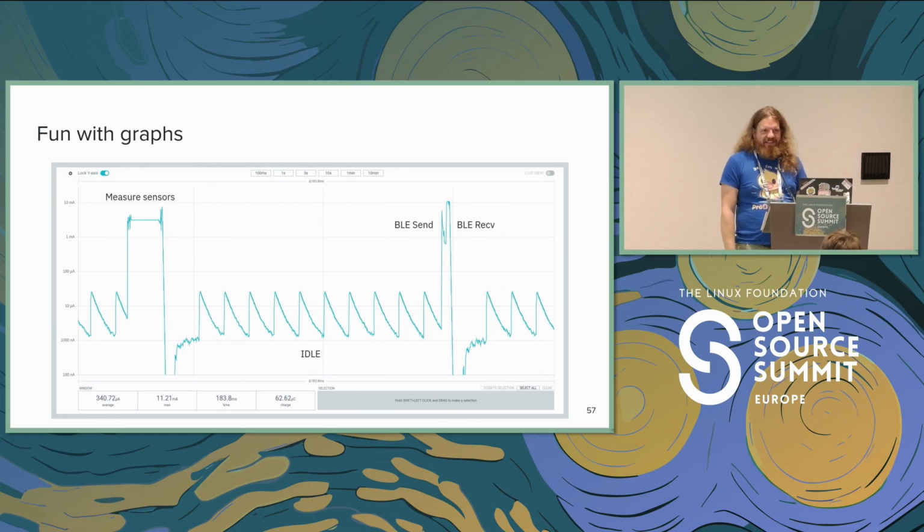Can you talk a bit about the CPU states? We saw standby, and there's one afterwards, which is shutdown. Do you have any support in Zephyr for that, like shutdown, which would be called hibernation, where you wake up from nothing?